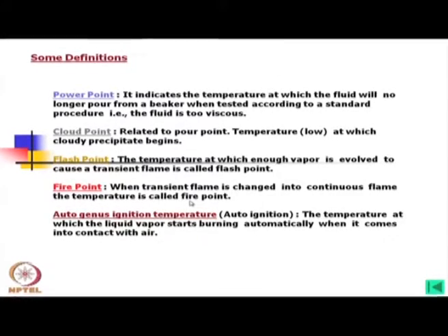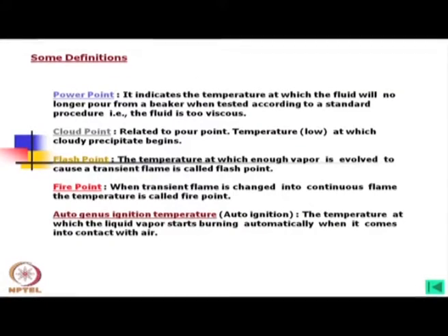Here I would like to mention that usually mineral based oil temperature may be up to 75 degrees for safe operation. Normally in our country, the ambient temperature in summer may be 45 to 50 degrees centigrade inside the factory, very hot summer. At that point, oil temperature may go as high as 75 to 80 degrees centigrade, which is very close to the flash point.